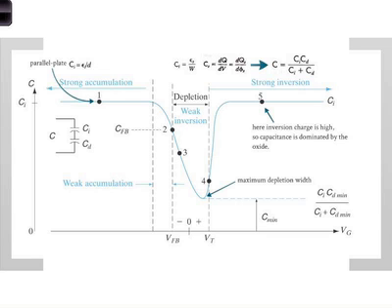So if you have a low frequency signal that varies very slowly, you have a different capacitance than when you have a very fast varying signal. So you have a low frequency capacitance that's different from a high frequency capacitance. That's a very important distinction, it turns out, and we'll come back and reiterate that in a little bit.